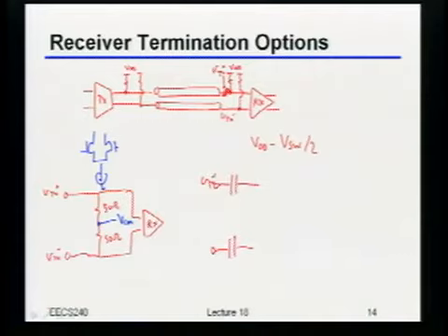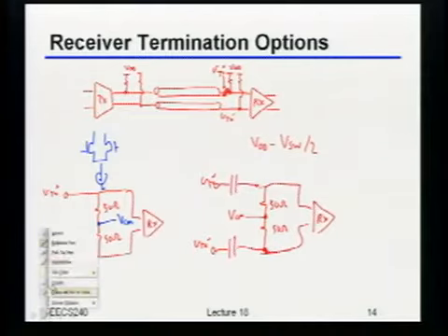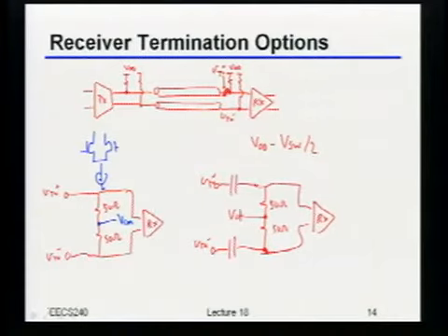All right, so I still have my VTX plus, my VTX minus. Now I still terminate these 2 in 50 ohms. And now to actually set the common mode into the receiver, I just tap off that center point right there. Right? Of course, these are tied together. Okay? Because now, since I have the AC coupling, this common mode voltage is totally independent, at least at DC, from what's happening at the transmitter.